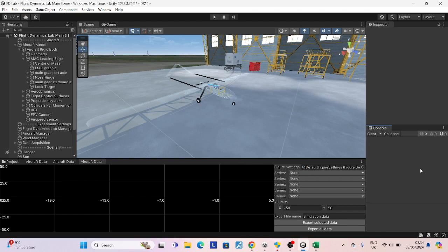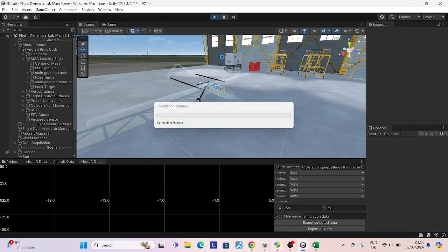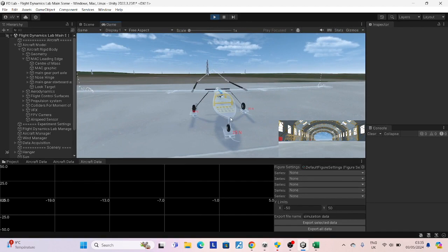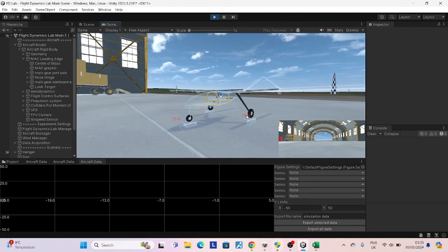Normally finding it directly without software can be a bit challenging. So in practice, we determine the center of gravity by measuring the reaction at the aircraft wheels. Here's how it works. We place the aircraft on scales that measure the reaction. We know the distance of the wheels related to the aircraft, and we know the forces. Thus, we can calculate the moment arm, and thus we can get the CG.